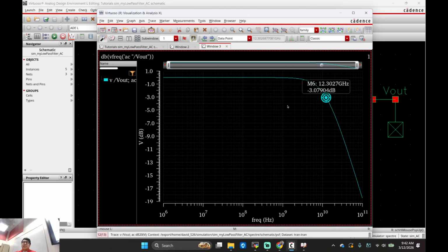Is that making sense? That's our 3 dB frequency, when our bottom term is 1 divided by, or no, it's 0.7, or 1 over square root of 2. Yeah, that's it. 707, or 707 millivolts. All right. You see that frequency, 12 gigahertz, correct?